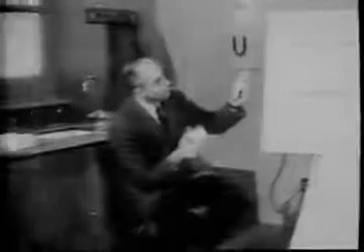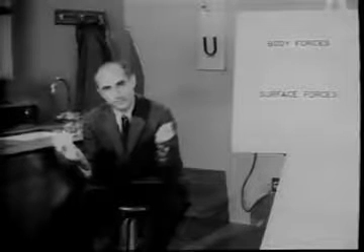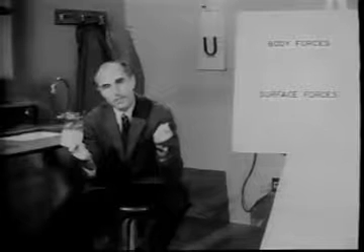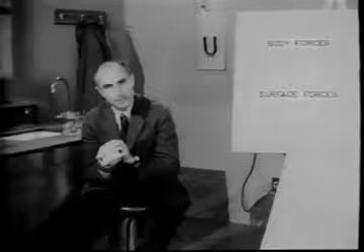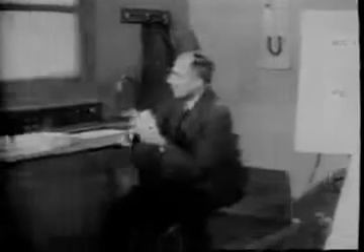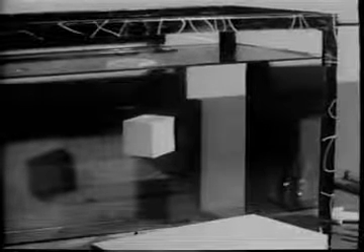Let this block represent, on an enormously magnified scale, our fluid particle. While many different kinds of forces may act on this particle, they may all be put into two categories: body forces and surface forces. Body forces act at a distance: gravitational, electrical, and so on. They act on the bulk of the material, hence the word body. If this cube were a particle of water in a quiet reservoir, it would be pulled downwards by the force of gravity. But the particle is motionless, so some other force must be present to counterbalance the weight.